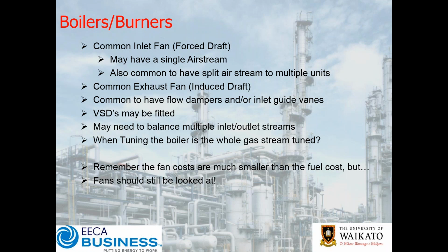And when you are tuning the boiler, are you actually looking at the whole system? Are you looking at the air side as well as the fuel side? Are you getting it right? Do you understand how the system curve on the air side changes as you get a build-up of soot and other material or debris, my apologies, through running the system? Is there something you need to do to tweak to adjust your airflow accordingly?